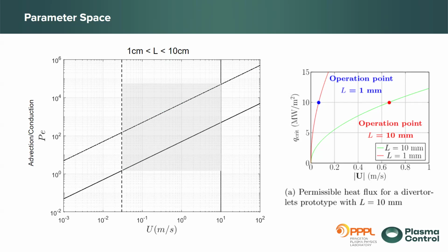Yeah. And then you can look at the Péclet numbers for how efficient the advection is compared to the conduction using the same tools. Then you can think about, okay, if you are operating at a few millimeters per second to 10 meters per second flows, how does that correlate, and how much heat can you advect.